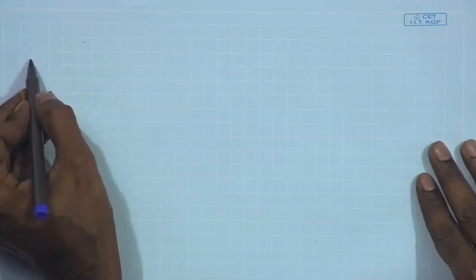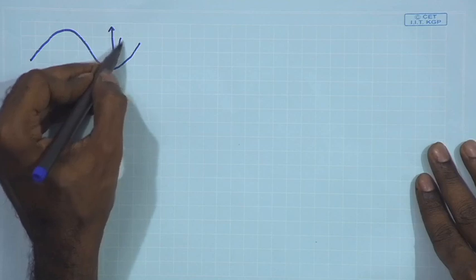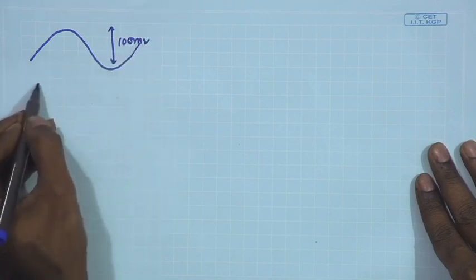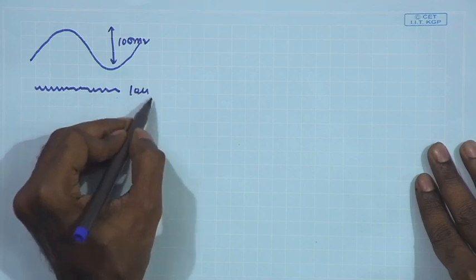Along with that, we have discussed in the beginning that the signal specification can have a very wide fluctuation in the baseline. If you remember the discussion in the beginning when we were trying to set the specification of the front end amplifier, we noticed that the baseline can have a huge swing, a few hundreds of millivolts, and on top of that you have the tiny signal sitting, which is maybe 10 microvolt or 100 microvolt.